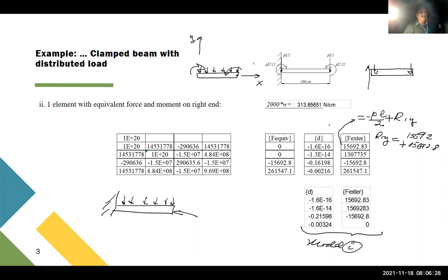And the problem is that here, we have concentrated forces on that end and concentrated moment. So that's error. That's error. And that's because we're using a very simple model, one single element for this problem. We have to be careful. So let's go now.